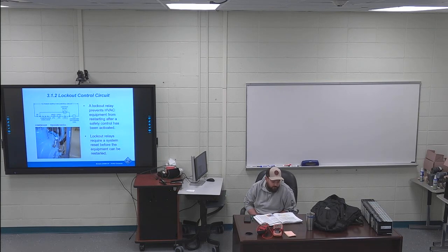Right-hand side of page 20, that second to last paragraph, the whole thing is highlighted. If the lockout relay becomes defective, it should be replaced with an exact duplicate to maintain the proper resistance balance. This type of relay is sometimes called an impedance relay.